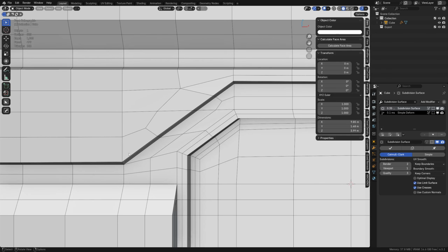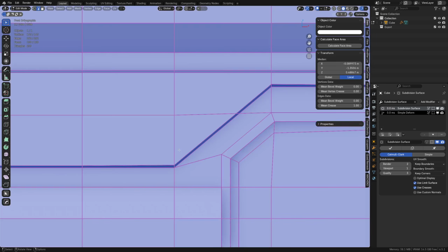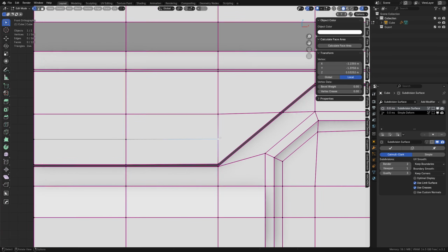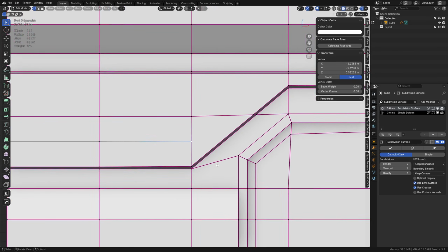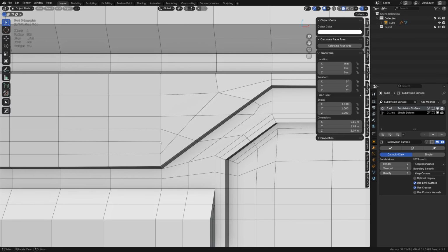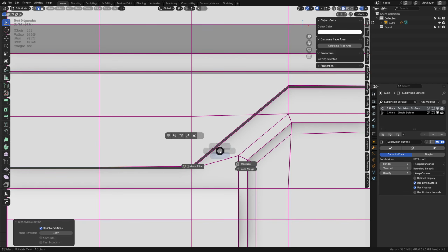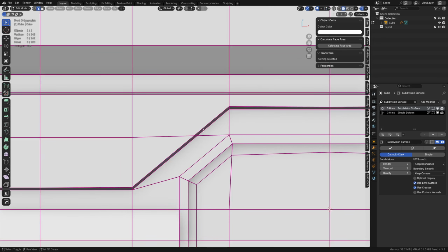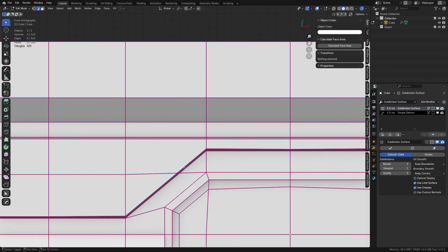But matter of fact, if you have a diagonal like this and you try to run edges through it, and you watch anybody doing a subdivision modeling video, they're going to go back and clean these edges up usually. And a lot of times the way they deal with these triangles is they end up just running an edge to the back of it, and they start doing stuff like this perhaps, right? And so what that does is it creates an end pole. It just shifts it over here. The triangles are an acceptable form of topology. You can see the same kind of thing happening here with edge flow. So this big n-gon here, though, on the other hand, a little bit maybe worse.